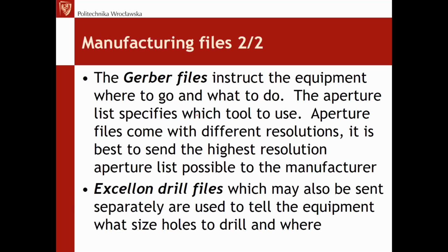For manufacturing of the PCB, we have Gerber files and the Excellon drill files. These are the files that are usually used. So it's not about PDF, although we can print a PDF. When you design a PCB board, you can print a PDF, for example, or make a print screen and make a bitmap file. But of course, it has no use for professionals. For professionals, when you want to deliver your project to a company, we always generate Gerber files together with the Excellon drill files, because they are together.